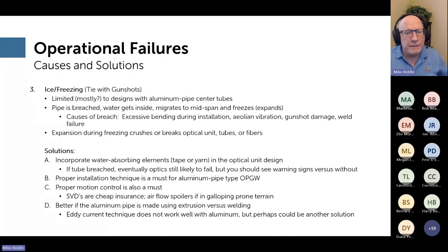When you're making stainless steel tubes, those are always a laser welding process. Very high tech, and they should have an inline eddy current testing process so that as the tube is being made, the weld is being checked. But eddy current works well with ferrous materials. It's highly debatable with aluminum. So maybe that's a possibility. I'm not sure.